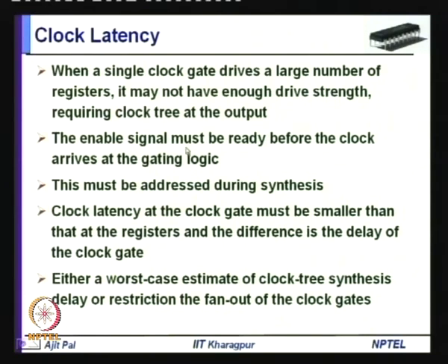So, the enable signal must be ready. Whenever you are doing that, you have to take the clock latency problem into consideration, because we have seen the enable signal must be ready before the clock arrives at the gating logic, and this must be addressed during synthesis. Clock latency at the clock gate must be smaller than that of the registers, and the difference is the delay of the clock gate. So, this type of stringent timing requirements has to be satisfied.